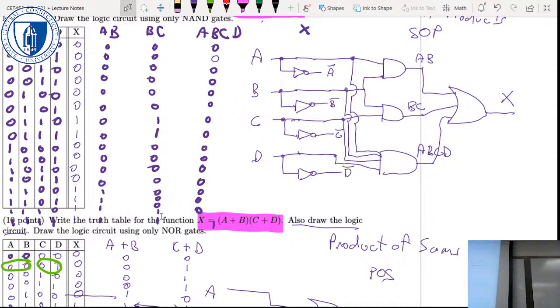So the reason. If I were implementing this circuit using those 74LS series devices, I think there exists a quad 2-input AND gate chip, but then I'd have to use a 3-input OR gate as well, as a separate device. Right?